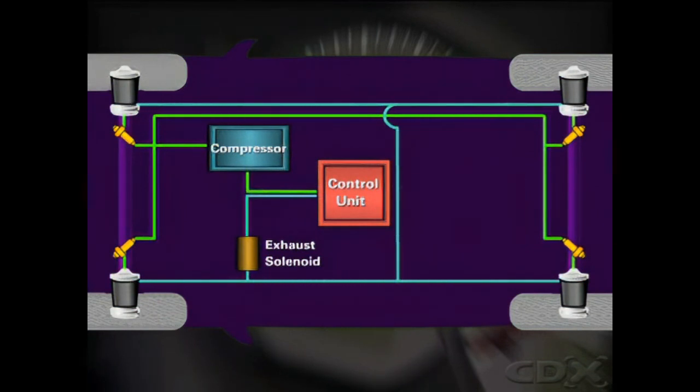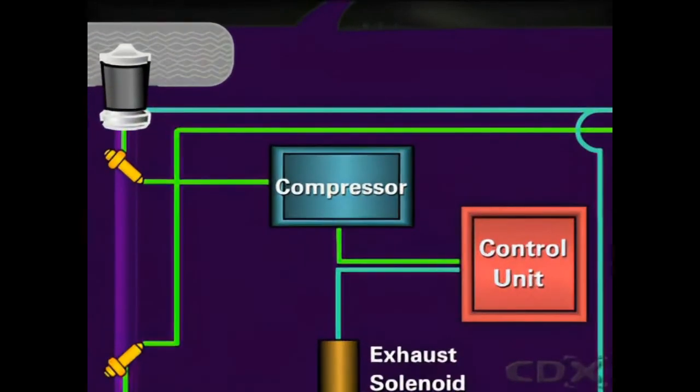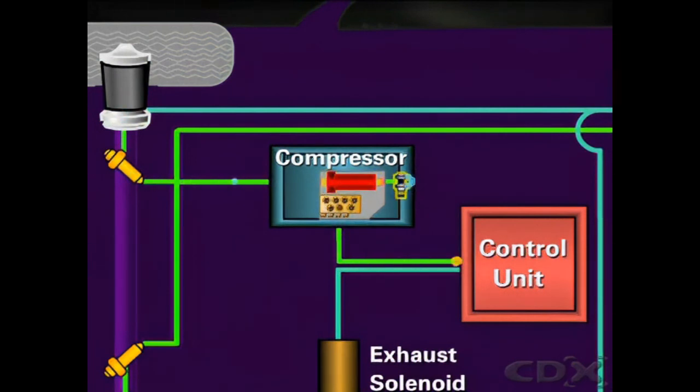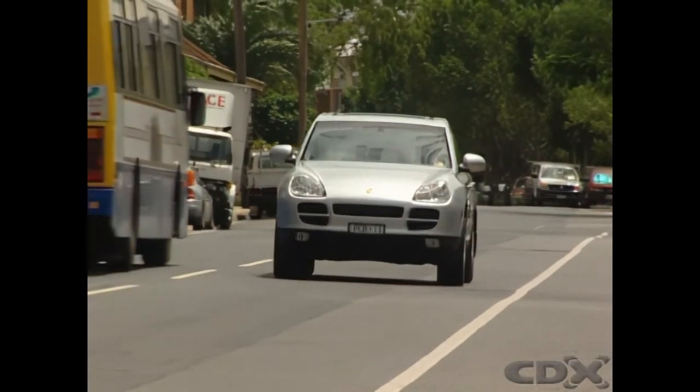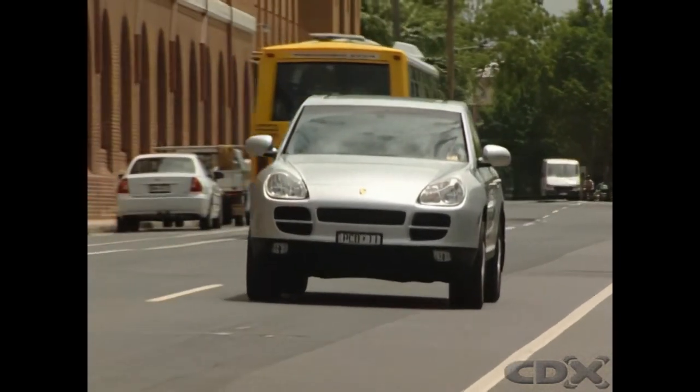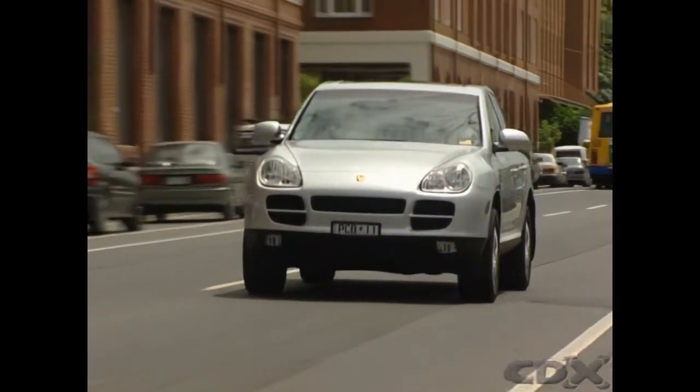When the vehicle is being unloaded, the solenoid valve block is activated. This results in airflow from the air suspension bellows being removed via the air dryer solenoid valve in the compressor, then via the relay valve. The air is then exhausted into the atmosphere. Any dynamic air spring movement while the vehicle is in motion is ignored and does not cause the control system to respond.